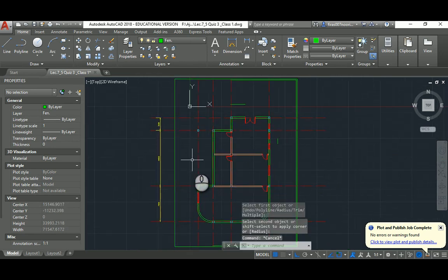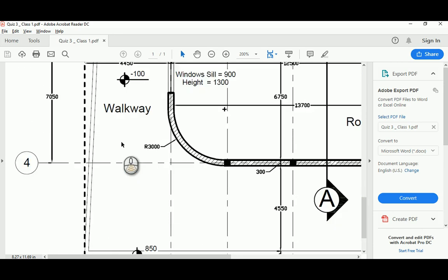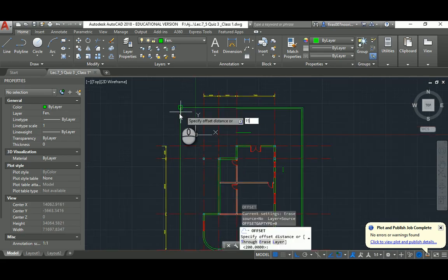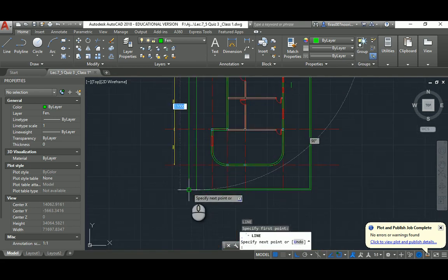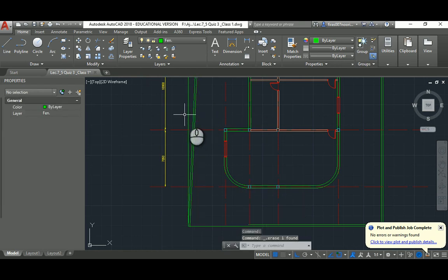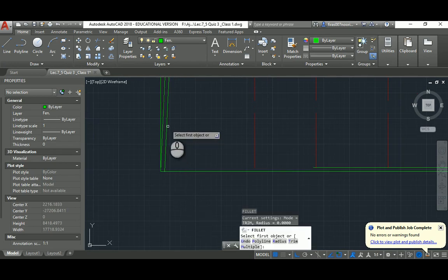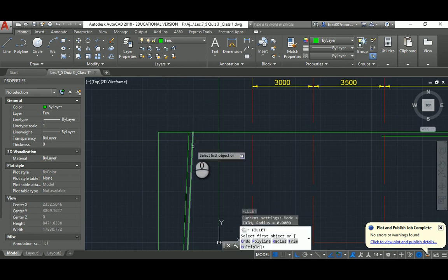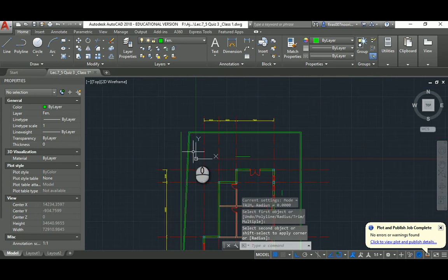Okay, now it's a 1500, and then you close the line. Okay, easy. Again, it's a 1500, and then you close the line like this. Offset at 200, remove those guys, and then fillet. I'll keep that actually. Or fillet this guy with this guy, and again I'll close that with that, and this one with this one. So that's my land, that's my fence, that's my land.